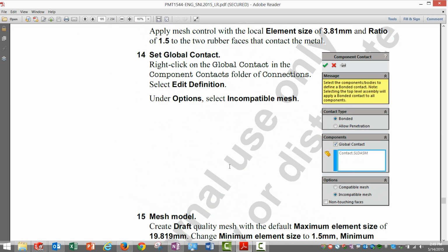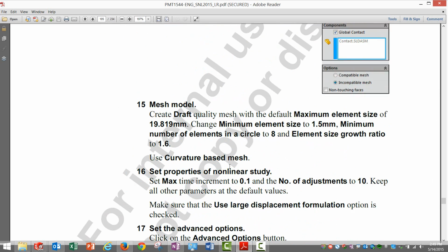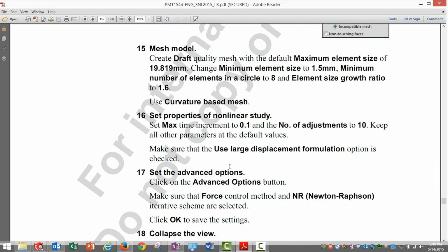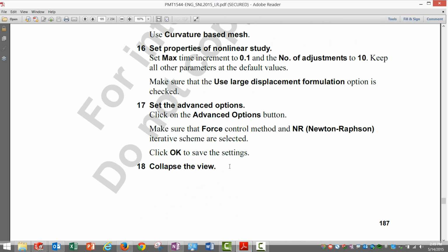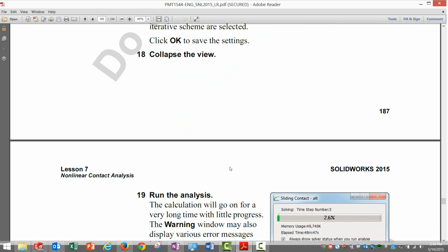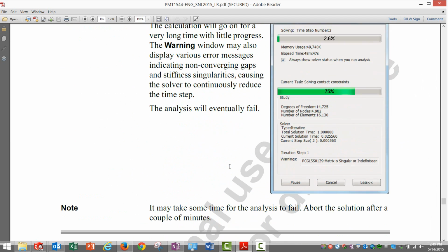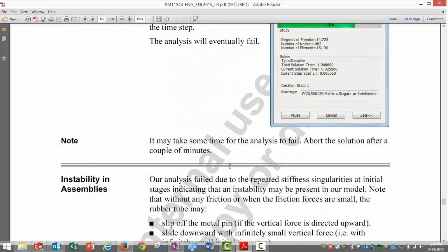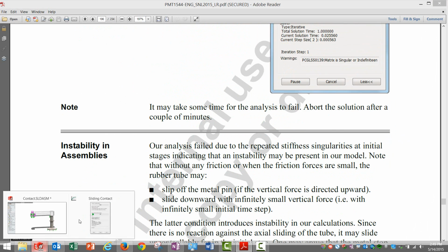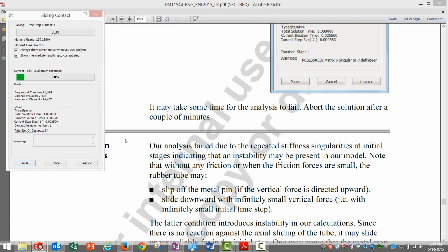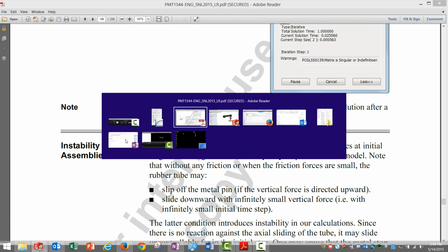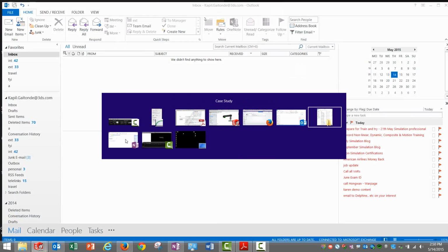And mesh controls, that's what I say. You can either give it at the component level or select the appropriate surfaces and give it. We want to ensure a finer mesh around. Okay. Yes, we can trigger this analysis. Frankly, it is a bit time consuming, but I am holding on to see a failure. I think the failure has already occurred. Let me check.